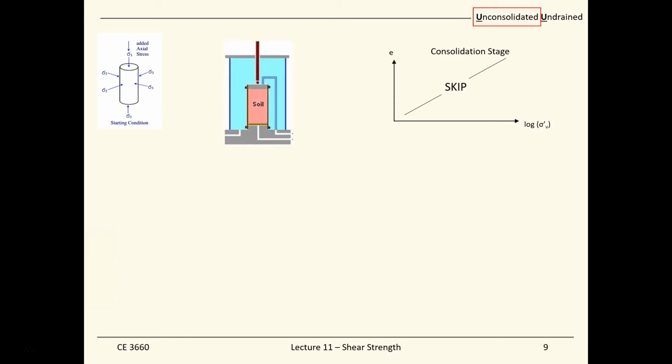And this is the laboratory setup of the triaxial apparatus for conducting unconsolidated undrained tests. You will find the soil sample is confined by a pressure chamber, and the chamber is filled up with fluid. It can be water, it can be oil. There's an outlet for this triaxial cell, and you can apply the cell pressure. So you can apply air pressure to your cell.